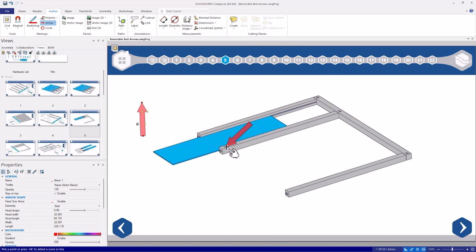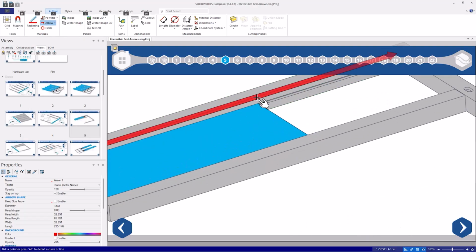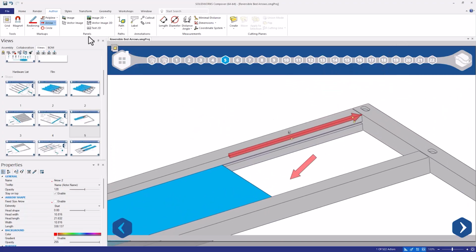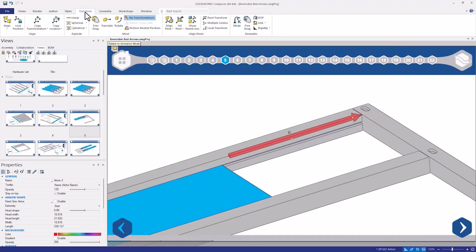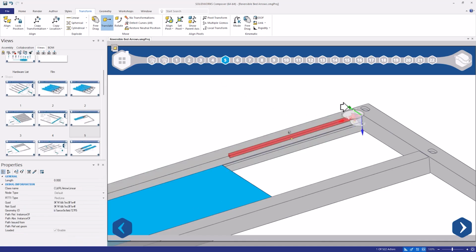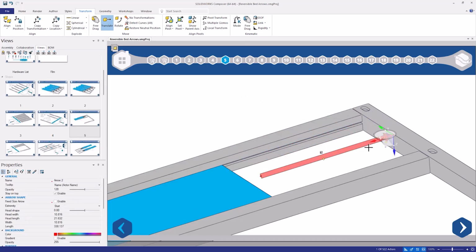Therefore, you want to detect curves. You can do this by holding Alt and hovering over faces or edges. It is worth zooming in and making sure you get the right edge or face though. Even if it's not in the correct place, as long as it's facing in the right direction, then we can move it easily into the right place with the Translate and Rotate tools.